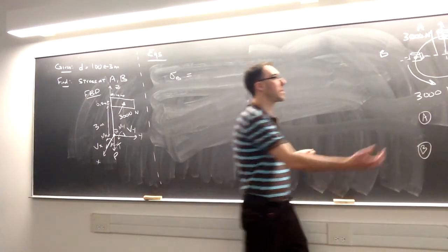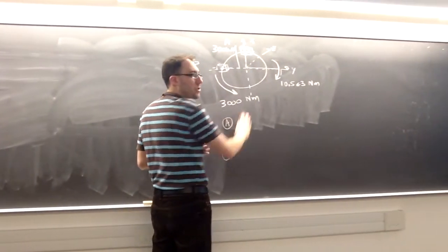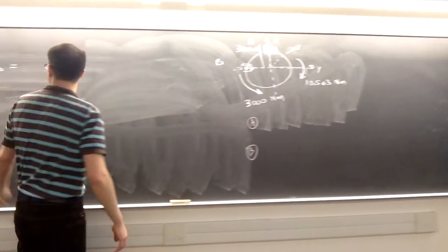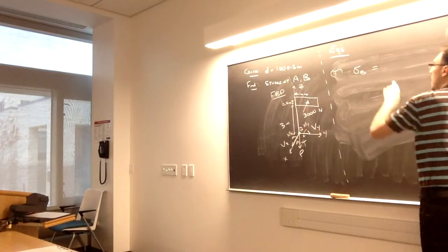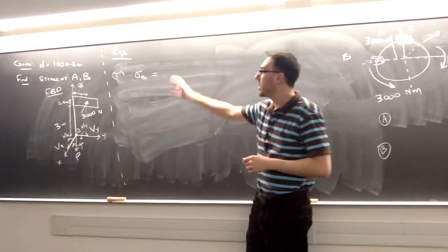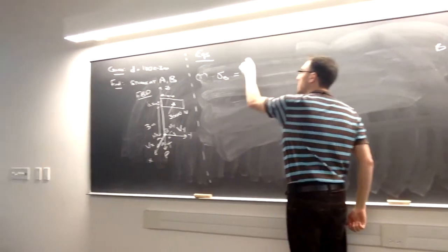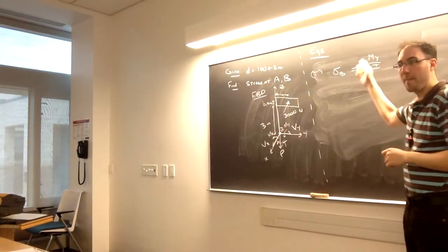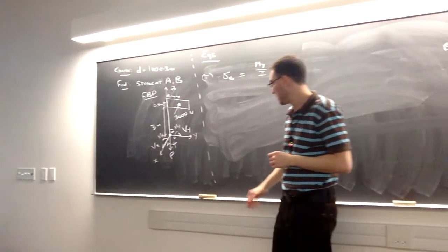It'll be tensile because at the top, it's going to be pulling this material out, and below the neutral axis, this moment will be pushing the material in. So we know at point A, this will be a tensile force. And remember, in beam bending, we want to use the negative My over I. Here we want to know from our picture already, is it tensile or compressive? And then use all positive quantities for M and y. So My over I, but we know it's going to be tensile.